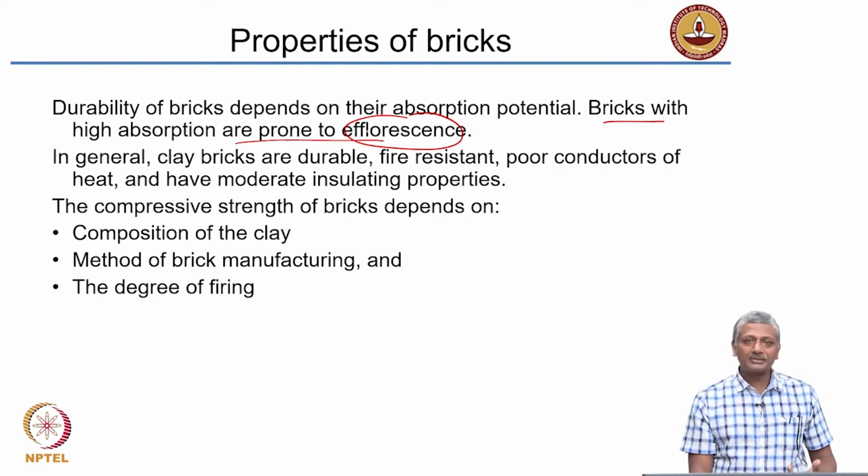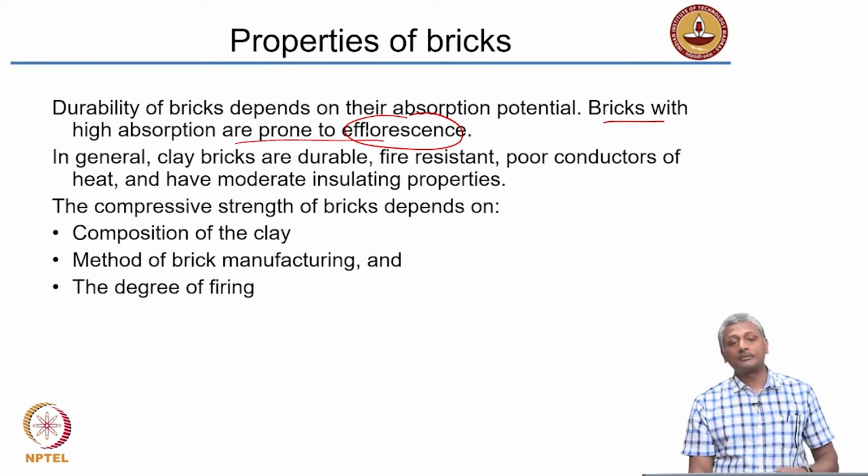Efflorescence actually means that we have some salts present either in the brick or the water that come up to the surface and then start crystallizing, leading to a very poor aesthetic quality of the surface.